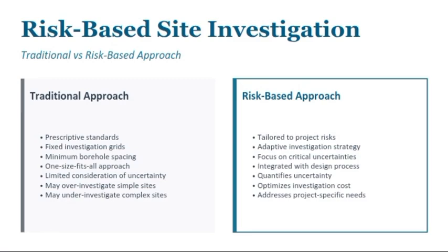Now, if a project involves a shallow foundation on a competent soil, extensive deep drilling may not be necessary, right? However, if the project involves soft clay, maybe landslide-prone slopes, or contaminated ground, or even a karstic limestone, then investigation efforts become more intensive. Why? The risks are higher.